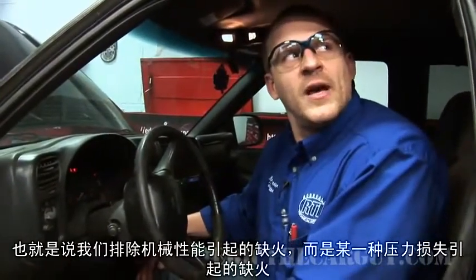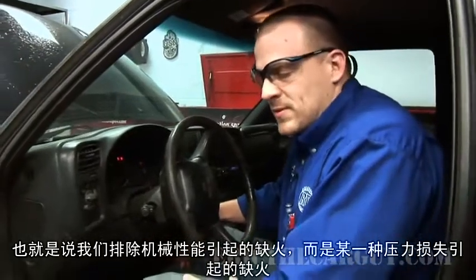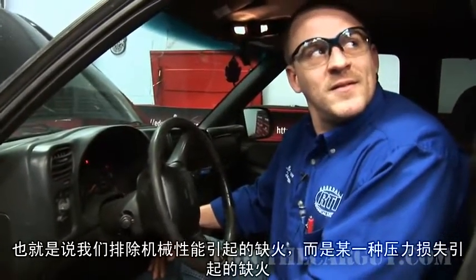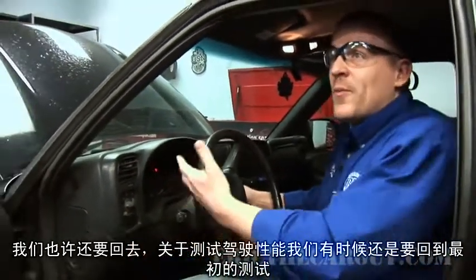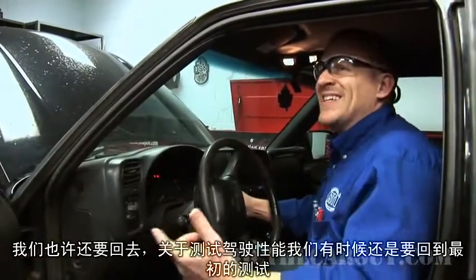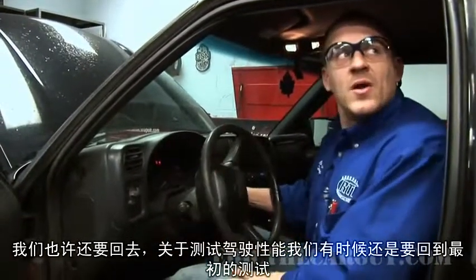Well, what you're trying to rule out here is a mechanical issue with the engine causing the misfire, like say a burned up valve or something going on with a piston, some kind of compression loss causing the miss. That's right. So again, just direction. Now we might go back to that. One of the things about doing drivability work is sometimes you come back to a test. You keep guessing until you get some evidence.